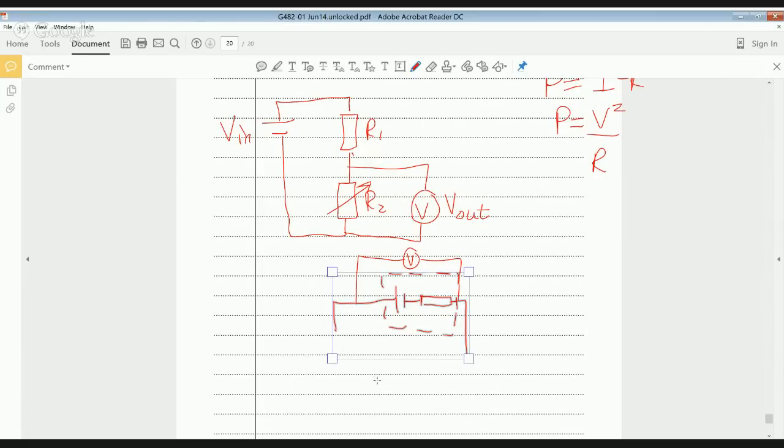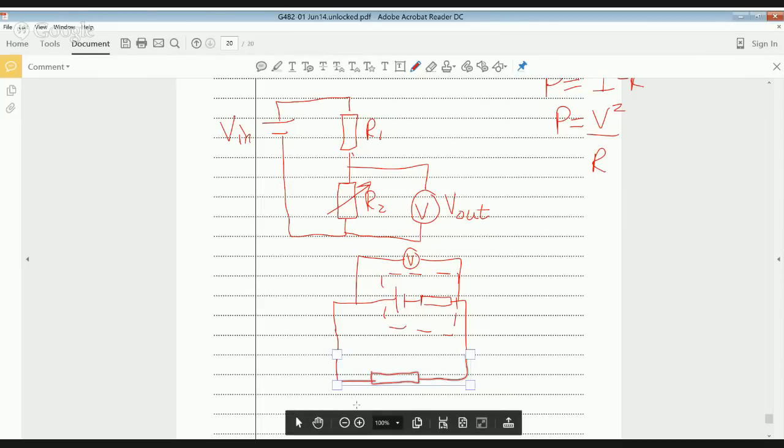Remember that if I connect a whole circuit up here, the voltage in every branch of the circuit is the same. So actually, the terminal PD is also the potential difference across this part here. How that differs from the EMF is going to be related to how many volts are lost by the internal resistance here. So you have the equation on the formula sheet: E equals V plus I little r, and little r is the internal resistance.